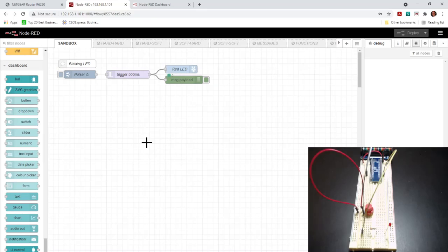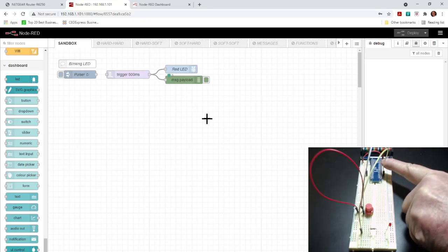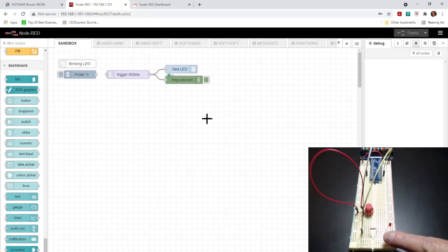So now our next step is to have more automated control over our hardware LED. We can see our hardware LED in our camera view inset, and the LED is off right now, and we've connected it from the GPIO port 12 over here to the input of the resistor to the LED.